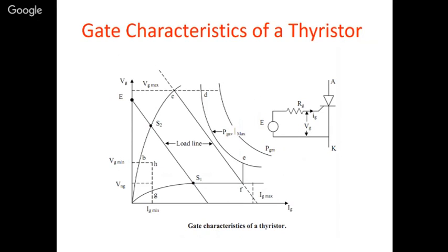In digital firing also, in the gate circuit, you will have the optocouplers for isolation purpose. You will again have the driver IC in order to drive that, because the supply with which you are giving the gate pulse, say my microcontroller, will give you only 5 volts.